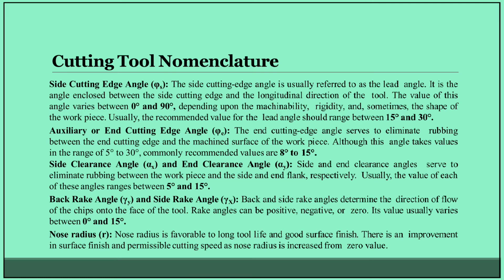Last one, nose radius, R. Nose radius is favorable to long tool life and good surface finish. There is an improvement in surface finish and permissible cutting speed as nose radius is increased from 0 value.